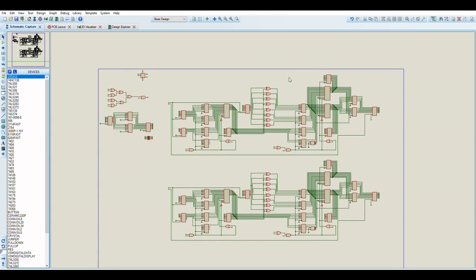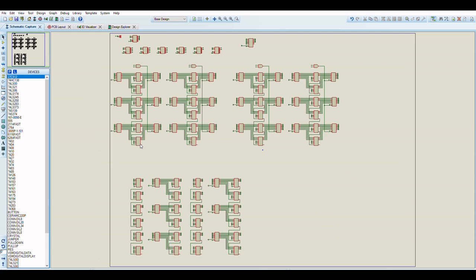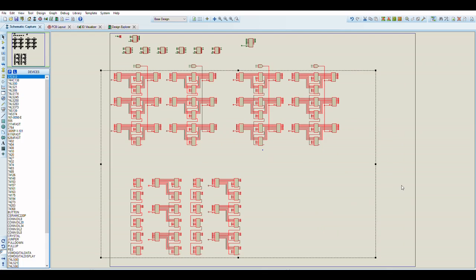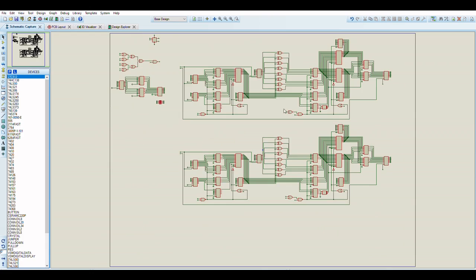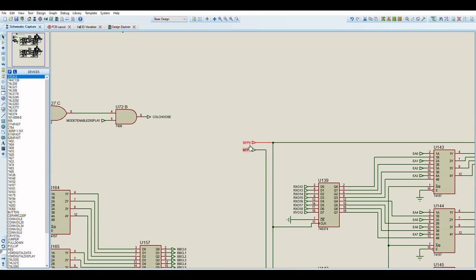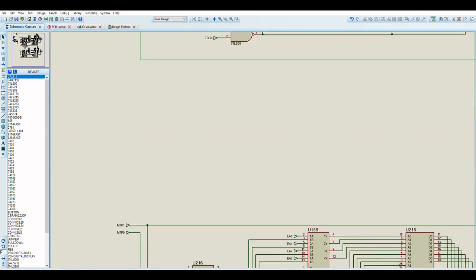So taking all of the time that all of this would have taken, plus the time needed to decode and read from the virtual tile screen to indexing the tile pixel data, was longer than 166 nanoseconds by quite a large margin. So that's why this is doubled up, and that's why the inputs for these 2 are alternated. So pixel 0, pixel 1 on this side. However, if I scroll down, it's pixel 1, pixel 0.